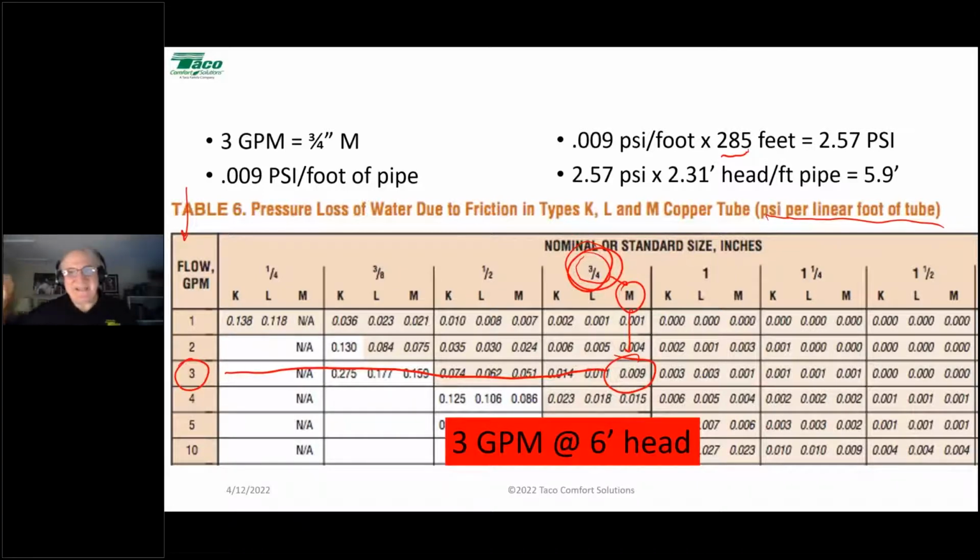Now, we see that as a problem more in domestic hot water recirculation systems. High velocity combined with high temperature, high chlorine content, running continuously, that'll make a mess of a domestic hot water recirculation system in no time. It takes a little bit longer in a hydronic heating system, because it doesn't run all the time, but it certainly can happen. Usually somebody complains about the noise before the erosion does happen, but the erosion is real and it can happen.